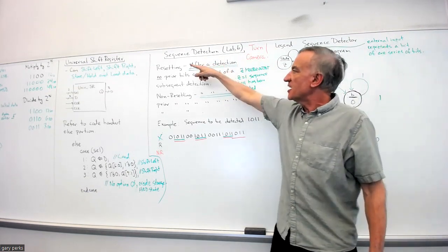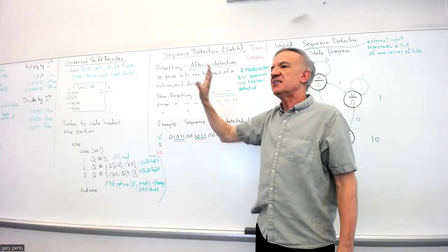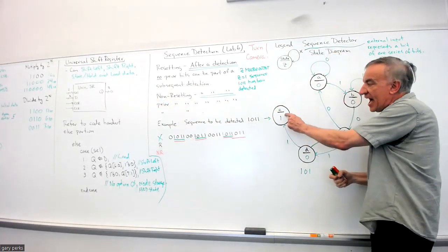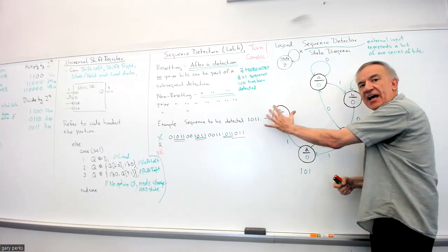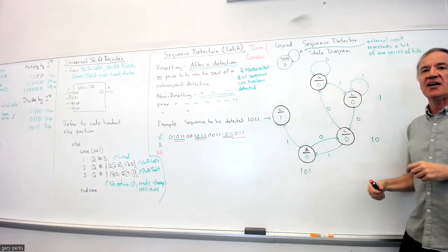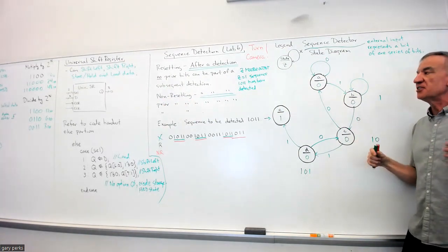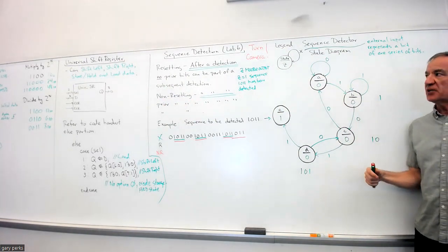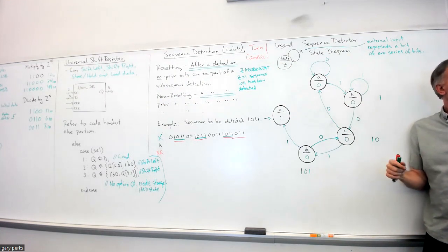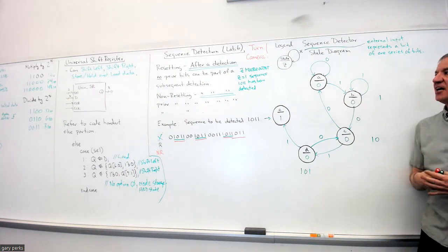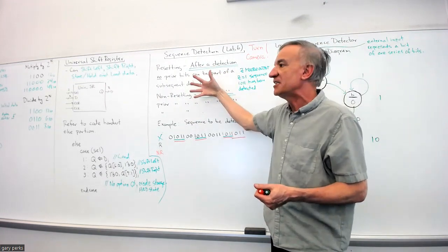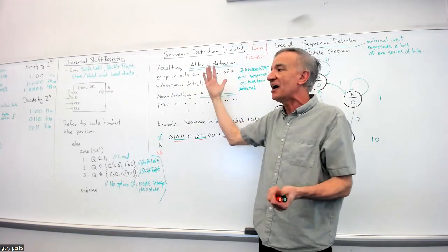The state diagram for resetting and non-resetting is different after you have a detection. So after state E, after we have a detection, we're going to have differences based on what type we have. But before you have a detection, there's no difference between a resetting and a non-resetting state diagram. They're both the same. That's why I said earlier, these three words are very important, because the differences don't come up until you have a detection.